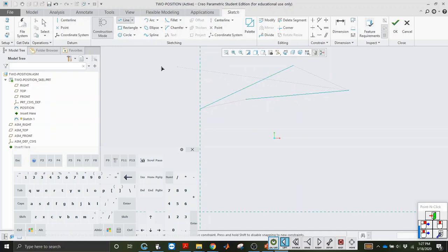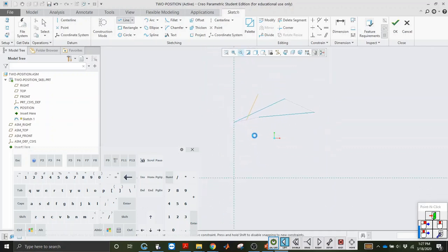In Creo 5, which I'm using here, it automatically selects references for you. That's why I didn't have to declare these lines as references. It just knew that I wanted to, which is pretty neat. But anyway, so now we have our 2 connectors, and now we want bisectors. Because it's a sketch, you need some physical object in the sketch that's not a construction line in order for it to be saved. So we're going to draw this nice little line through here, and the same thing. We're going to draw a perpendicular line until they intersect.